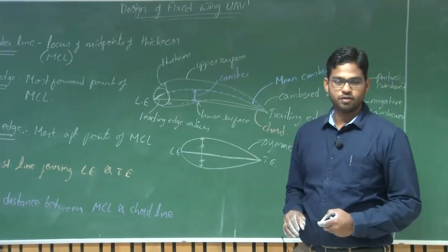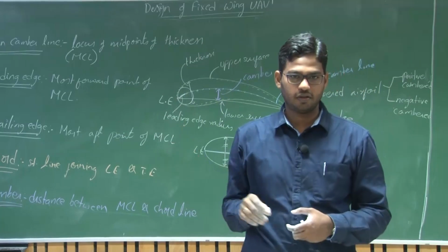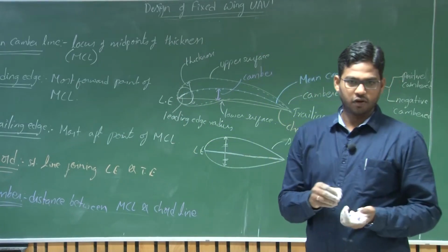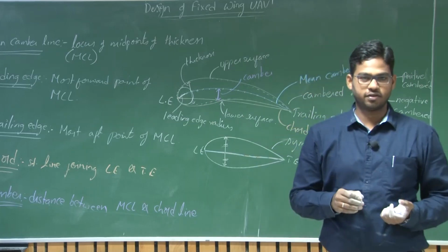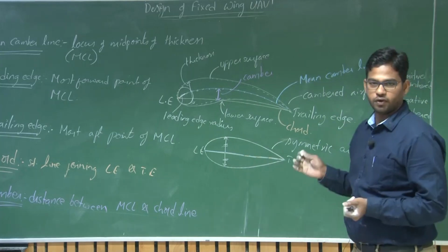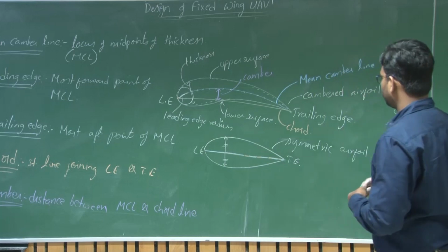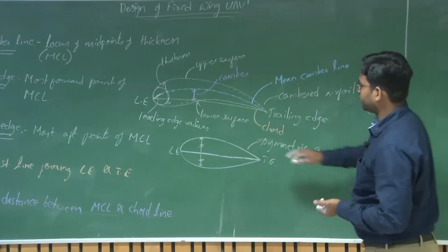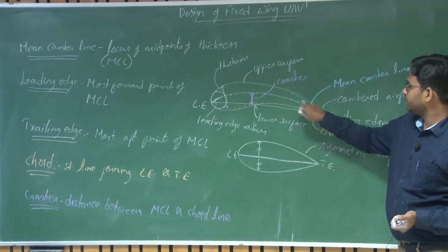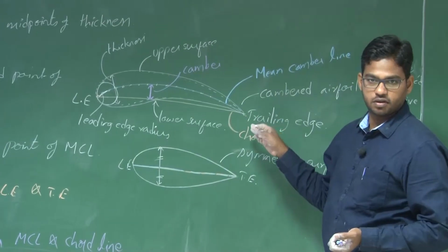Okay. Now how can I plot this airfoil? When I say plot here, I need the coordinates of the upper and lower surface. Or say, how does aerofoil software work? Say if you want to design a new aerofoil, what all do you need to do? You can see the camber is varying with respect to the mean camber line as the chord varies, right?